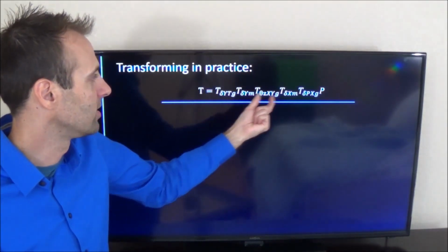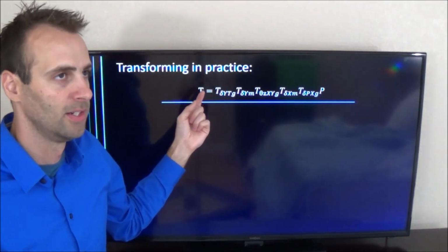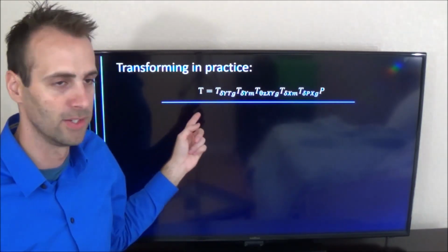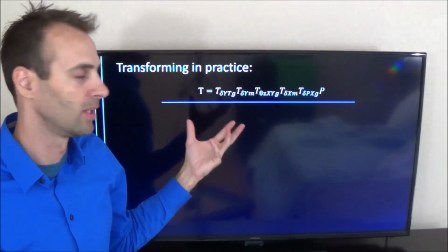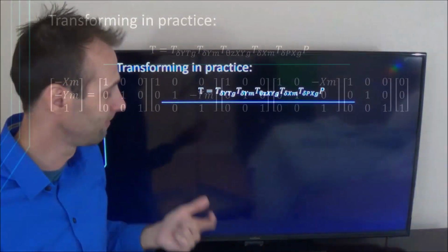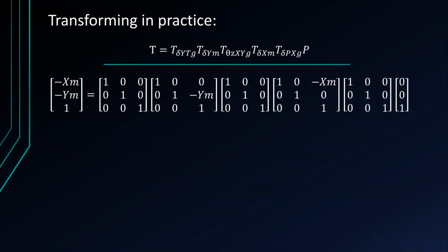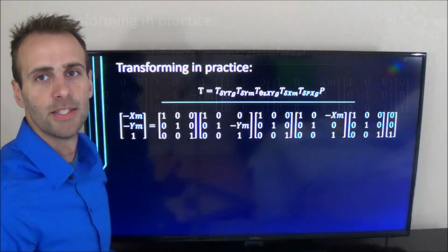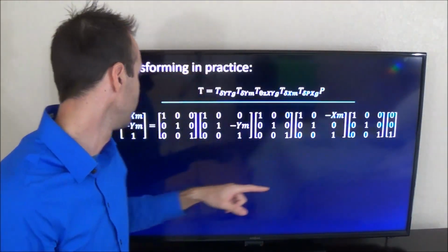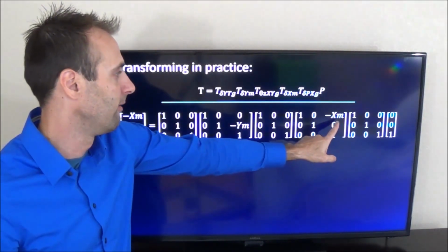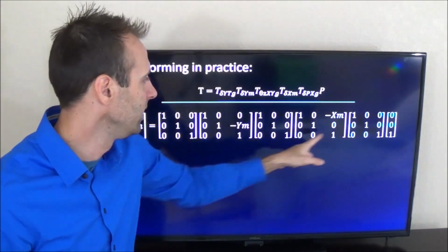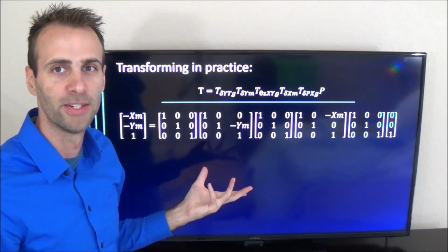So what I have here is a 2-axis machine with errors or offsets in between each machine element. I've got 2 axes, a part, and a tool, so I have 5 transformation matrices. Let's look at this in its expanded form. Let's say I'm at 0, 0 in the part, and I have my measured motion here and here, and each of these is the identity matrix, so it does nothing.